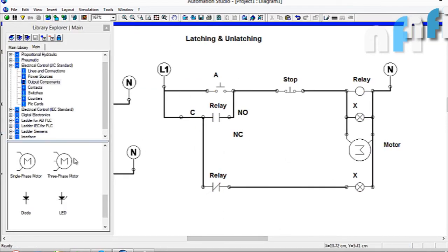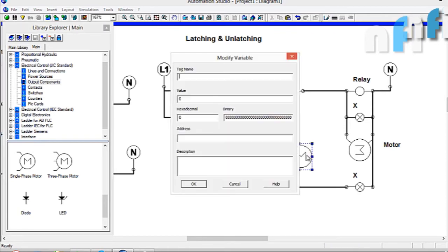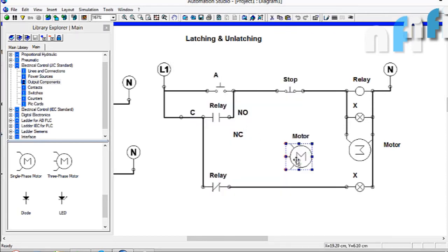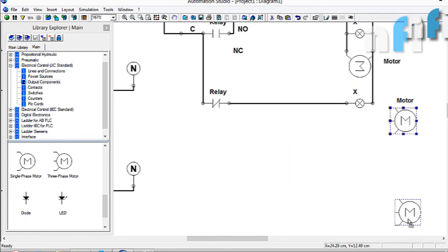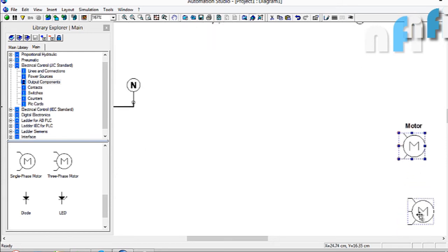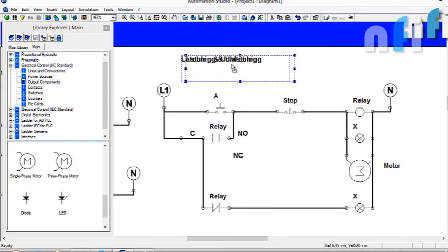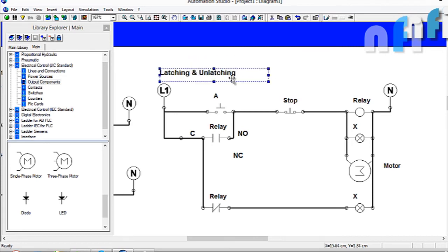Now what about the three-phase motor? Suppose you are having a three-phase motor, how will you latch that? Now that's the question. So for that we use contactors. Alright, I'll come to this three-phase motor later. Let me show you another main function of relay, which is called interlocking.